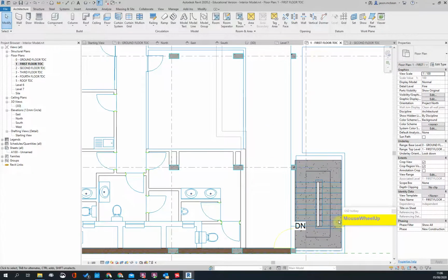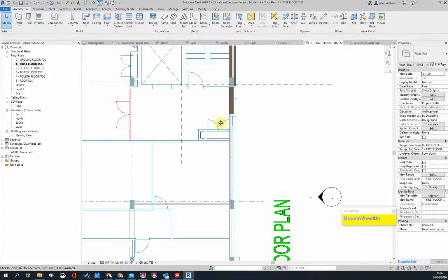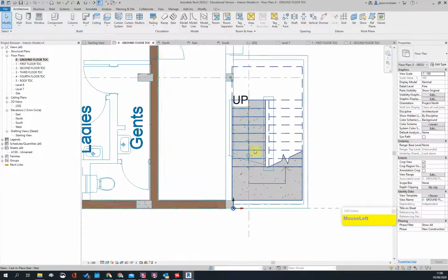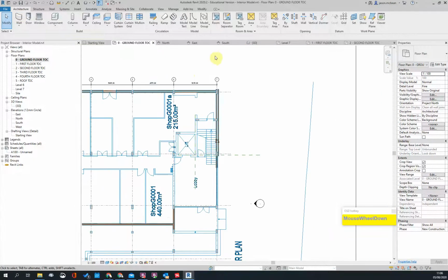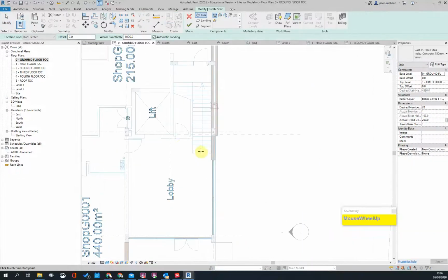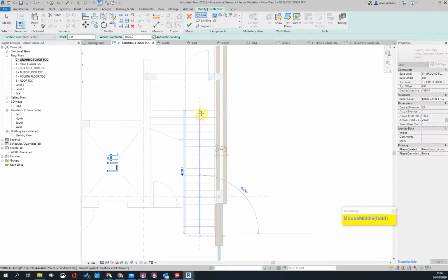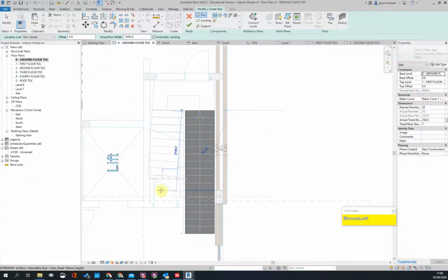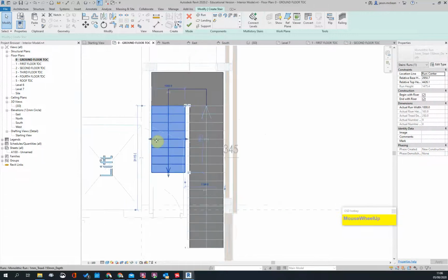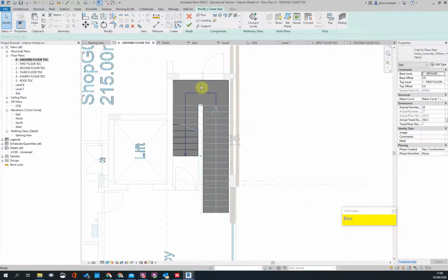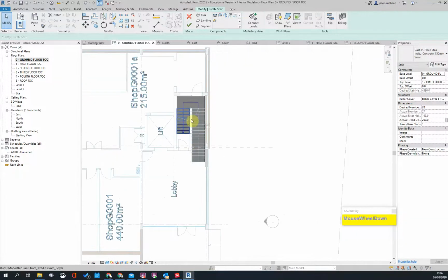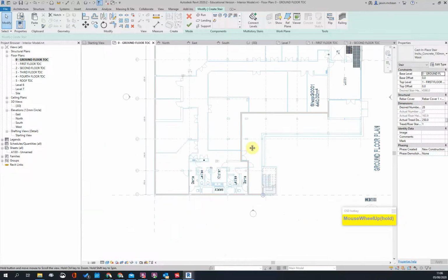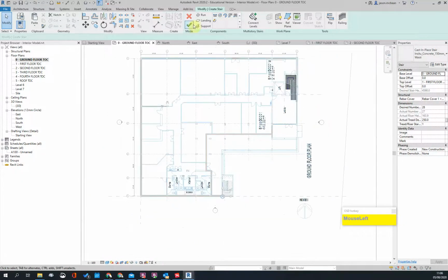So that is correct. So you go around, up and down. This step over here, so from ground floor to first, it's going to go this and then back up. So I'll do the fine tuning of the steps a bit later on. But in essence, I'm just establishing where they start more or less. So it'll go to there and then go from here. I'm going to stop at 1 short. Okay, and I'm going to move this. It creates the landing automatically. We might have to recreate some of these sometimes because of the way the landing works, but in essence, that stops at the correct level. Okay, so for now, on that level, that's all we have.